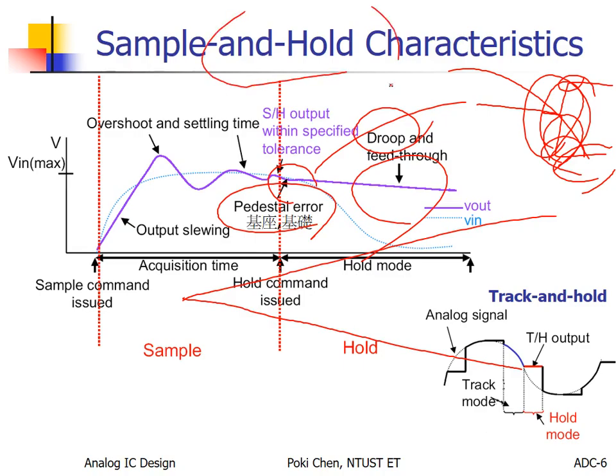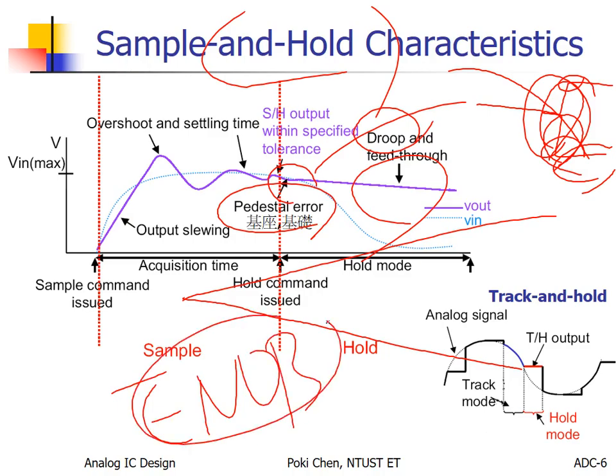Anyway, as analog IC designers, you need to face all kinds of defects. Many kinds of small effects will have an overall high enough impact to make your ENOB become very bad. So you need to deal with all those small issues. Small ones after accumulation can kill your performance. So you need to solve all of them one by one.